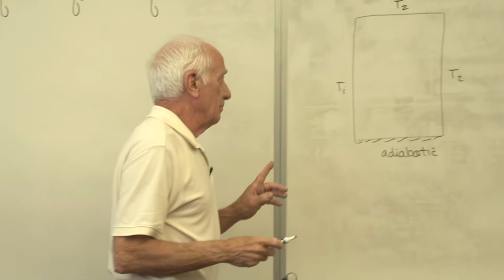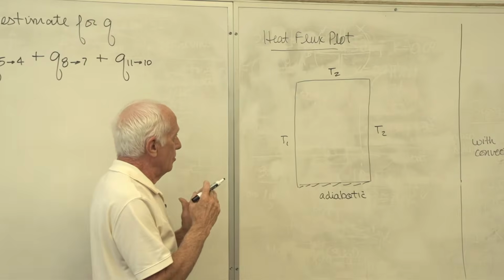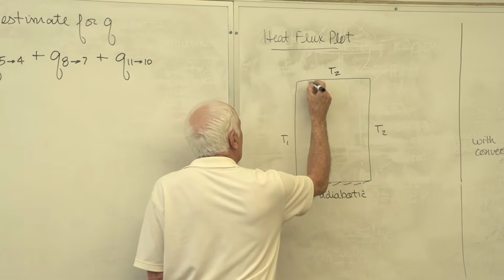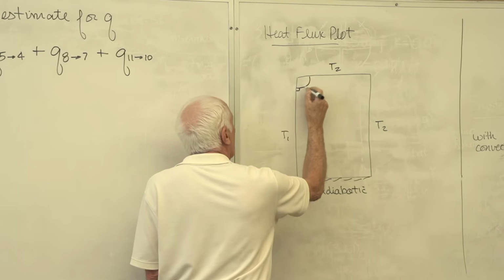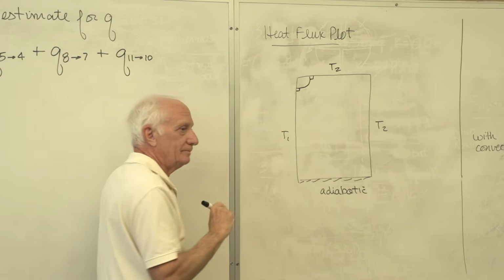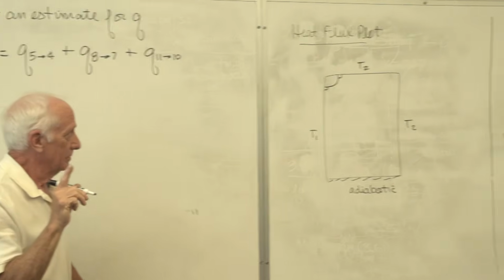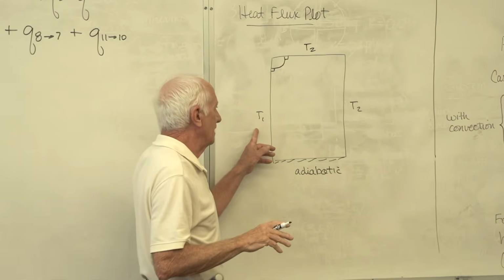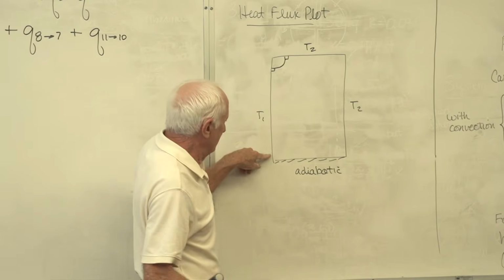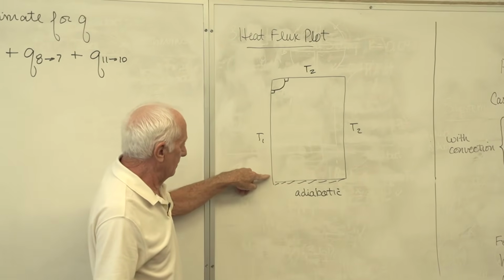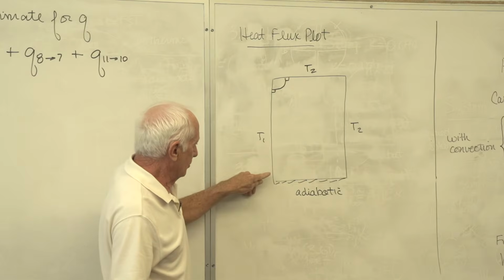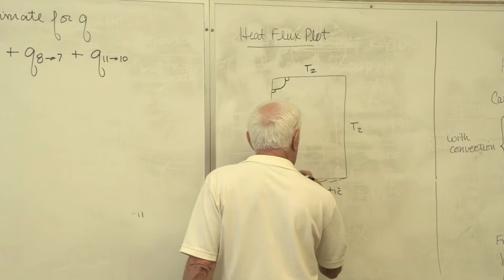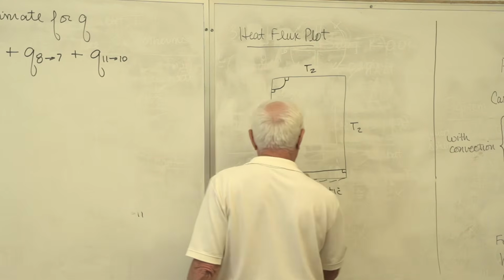All right, but here's something we did twice already. We said, you know, where two corners come together of different temperatures, the heat pretty much flows around, the closer you get, almost like a quarter circle. So I know that one. At the bottom, this is adiabatic. Let's assume T1's hot, T2's cold. Heat comes in near the bottom of the hot surface T1. It can't get out the bottom. So it pretty much travels along here, somewhat horizontal, like that.